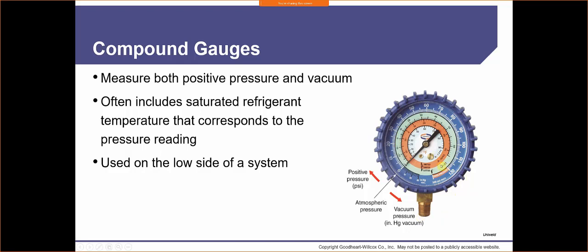Most of our refrigerant, if we're working on residential, is going to be R22, unless it's a new refrigerant, then it's 410A. The nice thing is we've got this inner chart. So how this corresponds is, if at 40 psi, based on the chart, I'm going to guess in between here, I'm going to say 17. I'm going to have 17 on the R22 scale. So the saturation point, or the boiling point for R22, is 17 degrees. So I know at 40 psi my refrigerant is going to be 17 degrees.